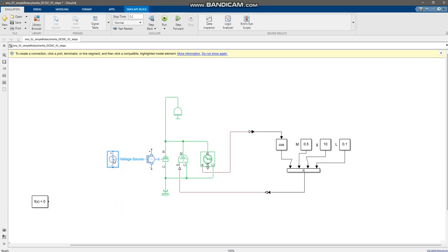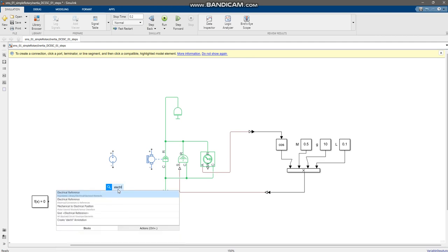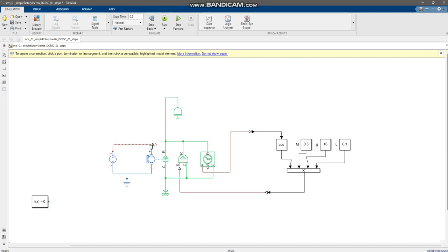And we are forgetting something over here. Just like on the mechanical side, we need the reference. That's kind of like a cardinal rule with Simscape. We need an electrical reference. Electrical references are available from the foundational library and from the electrical block set as well. I'll choose the second option, since I advised you to do so during the physical lecture, but I have found out that whichever choice you choose, it doesn't really matter. So that's done. References are done.